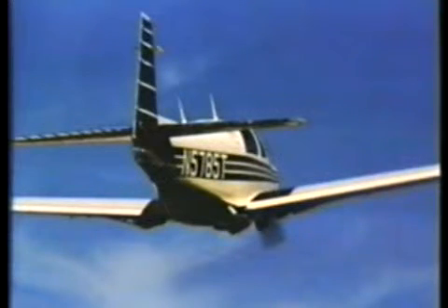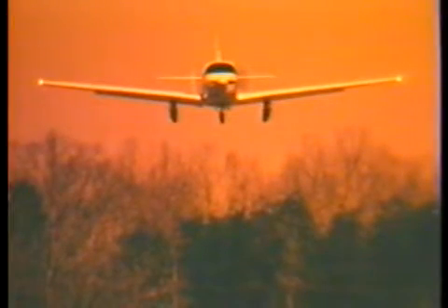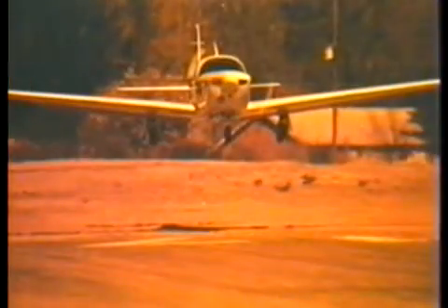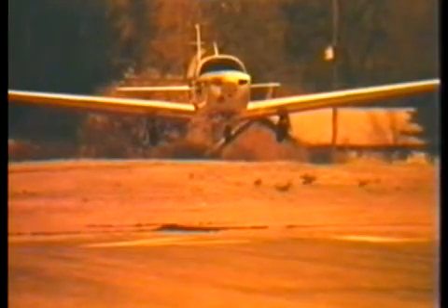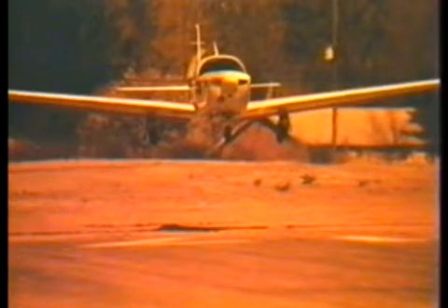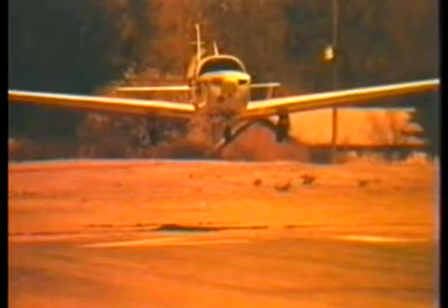What we're doing here is setting you up on final approach while you're still at max landing weight. Now we're going to ask you to come in over the fence at 1.3 VSO at max landing weight. Okay? As we explained a few minutes ago, you have to complete the transition from the approach attitude to the landing attitude. Everything is going by the book. The approach looks great, and your touchdown's right where you intended it to be. No overshoot, no white knuckles, no sweat.